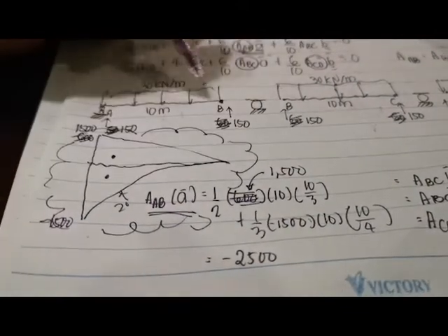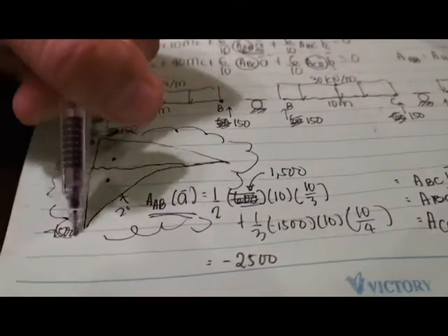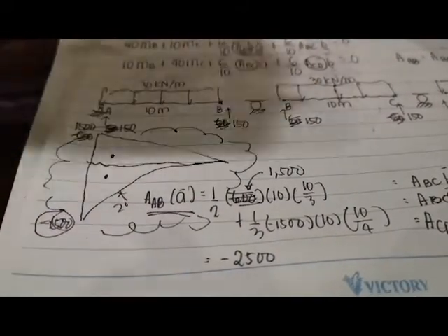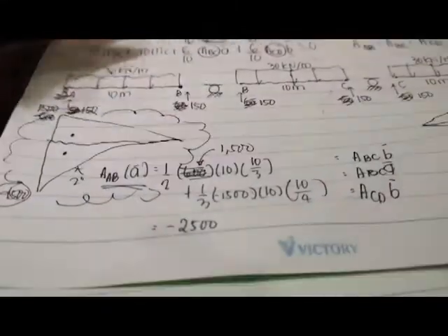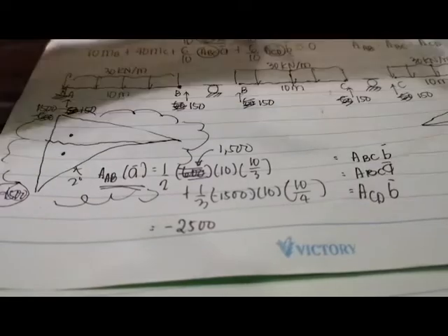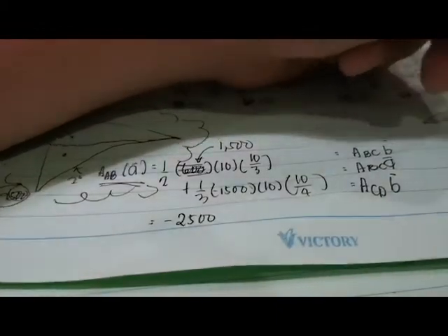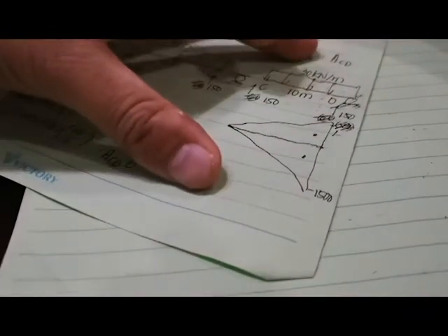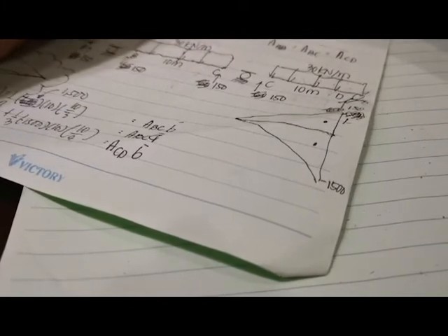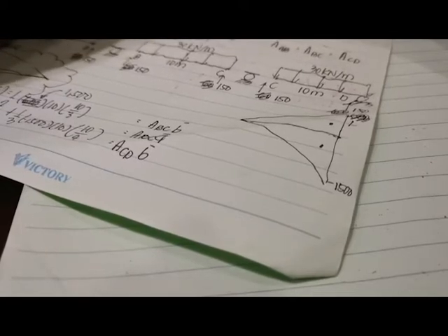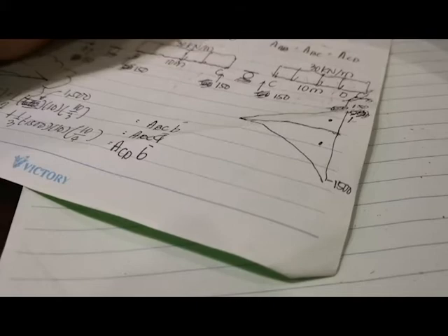Okay, and due to the uniformly distributed load at point A, this is also equal to 1,500, but negative. Also on span CD, since the measurement of the centroid is from the right, I did the same thing and made the moment diagram by parts. So they are just the same. So we are able to know that all first moments of area are just the same.